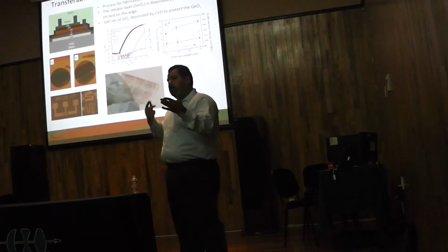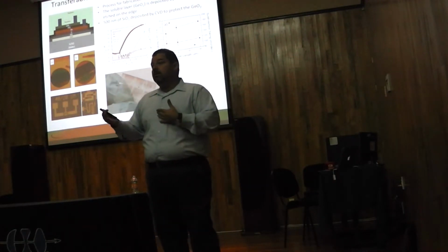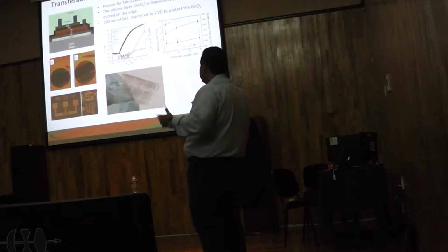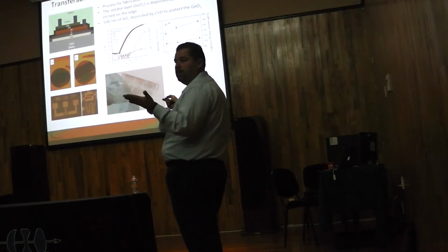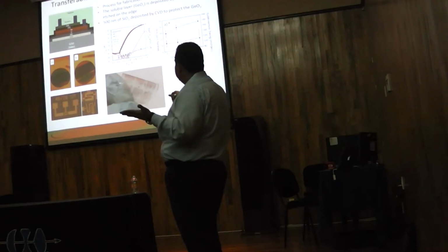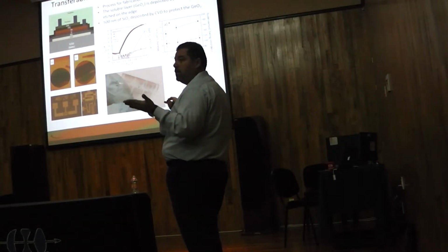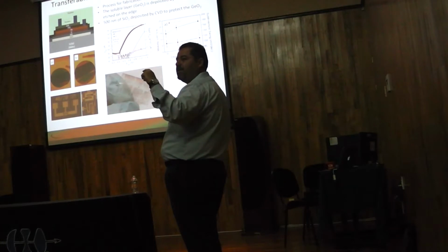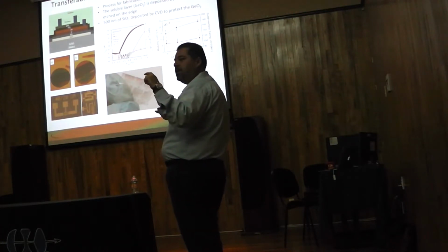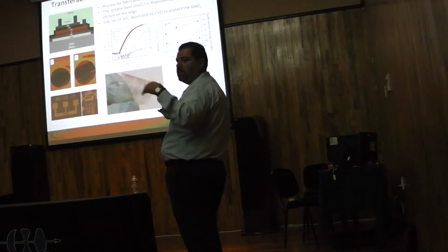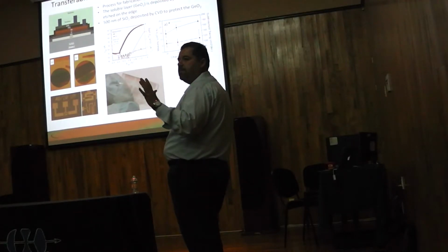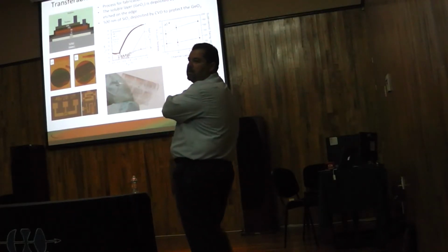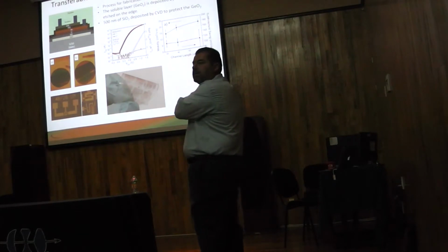Remember that at the beginning of the talk I mentioned the transfer process. We also do that, and that's very simple. Basically, what we have developed is this: this is the silicon surface, a silicon wafer, so it's a rigid substrate, and then we deposit by sol-gel a germanium oxide film about 1 micron. Germanium oxide is soluble in water. That's why germanium never made it as opposed to silicon. And then we do the entire processing. We don't really care about temperature anymore because it's on silicon, right? Silicon we can process up to 1300, 1400 Celsius.